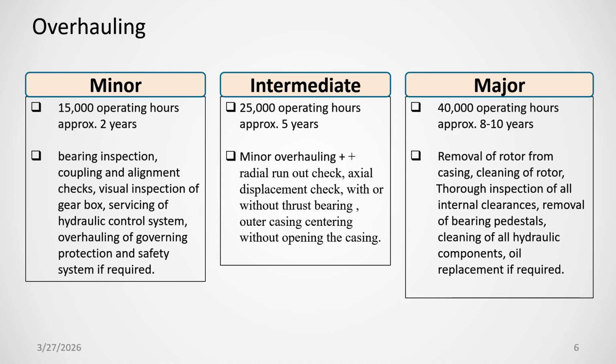For the outer casing and rotor, you mount the dial gauge on the rotor shaft and put the plunger on the rotor casing machined surface, and check the reading. If the readings match the protocol reading, that means it is okay. Otherwise, you can do a minor adjustment. There is a threaded cap and bush there that I have already explained. You can slightly move the turbine rotor up and down with respect to the casing, and the axial thrust also by the rotor thrust bearing